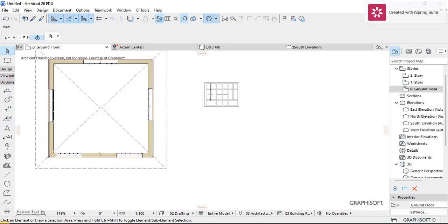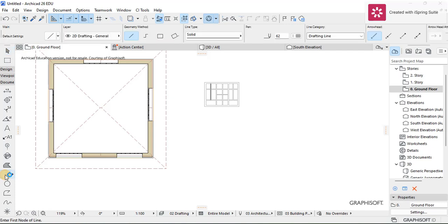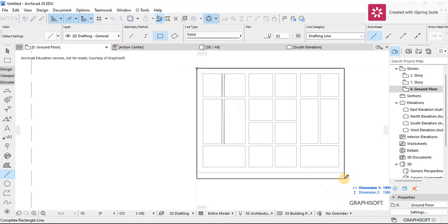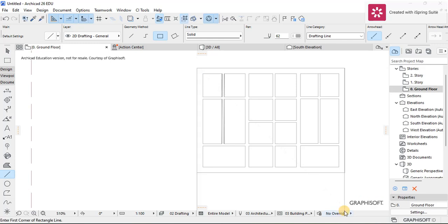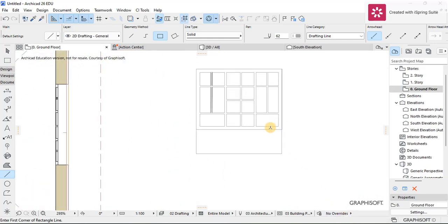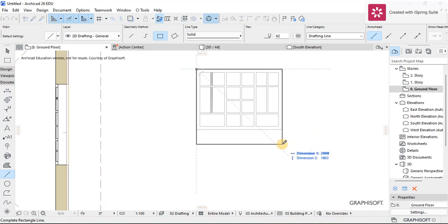So I'm just going to draw again the section for the door that I want to use. Let me highlight this area here, and then I'm just going to make it longer. So let me tab, and then I'm going to make my door 2100. So yeah, you can see this is my door. No, it was Z. I want the height, not the width. So tab it, then go down, and then 2100.